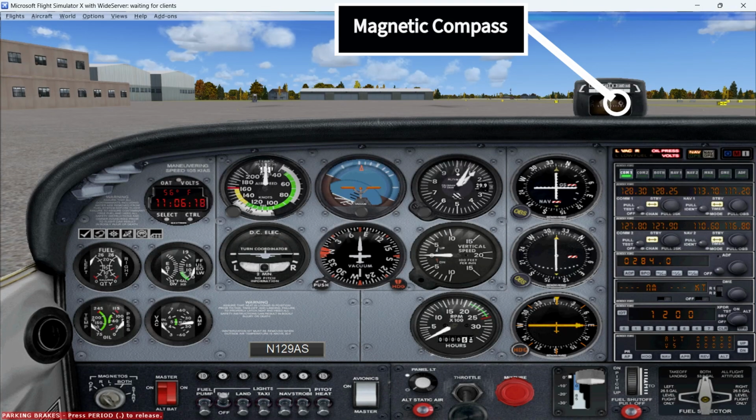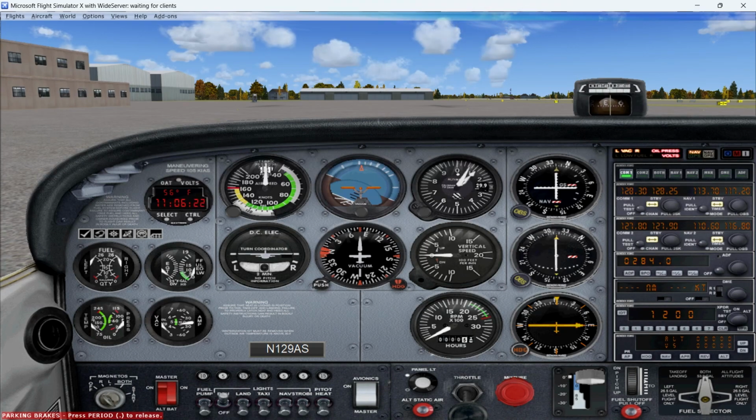Magnets in the compass cause it to align with the magnetic North Pole. It is nearly always fitted on top of the visor that shades the instrument panel, or is hung from the top of the windshield frame of the aircraft in order to keep it as far away from electrical gear as possible. The compass shows the 4 cardinal headings shown as north, east, south, and west.